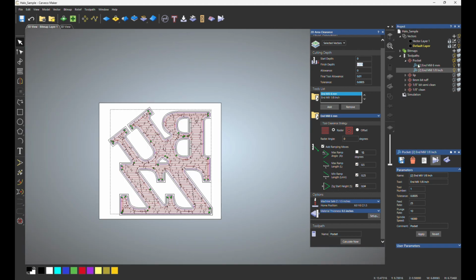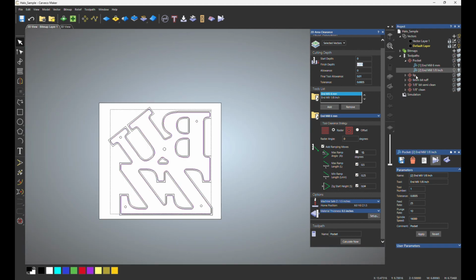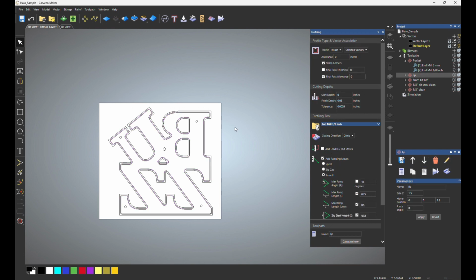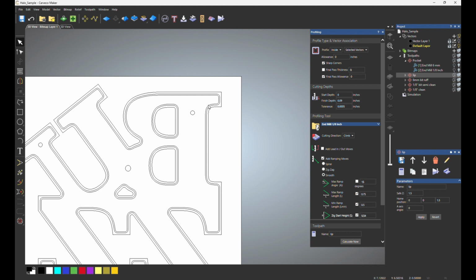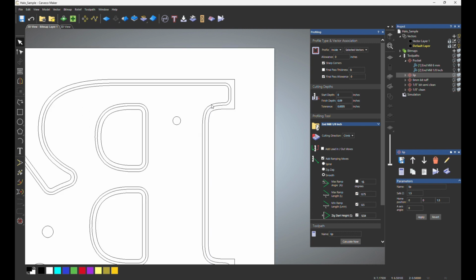Selected this, so the next one, we'll turn that off here. The next one will be this lip. We want to select the lip. It's going to have a 0.09 depth. The material I will be using for that is 1/8 inch acrylic, 0.125 of an inch. But if it sticks out a bit out of the back, it's not a problem. It actually helps a little light shoot out to the sides a bit more.